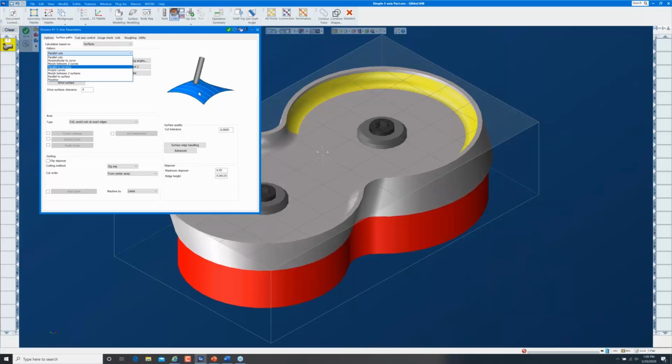It's very similar to a lace cut in 3-axis surfacing, except it's in the 5-axis world. We can create toolpath perpendicular to a curve, or we create some sort of curve, and the toolpath will always run perpendicular at the point at which it crosses the curve. The curve does not have to be a straight line like this shows. It can be a complex curve.